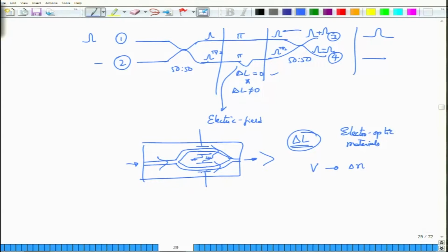However, when you make the phase shift pi, that is one of them is pi, the other one is 0, then they will be propagating, but the other one will shift its sign because there is a pi phase shift, and when you combine them you will actually get 0 output. Okay, so this is the waveguide device analogous to the fiber Mach-Zehnder interferometer.